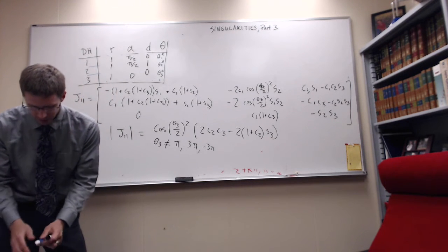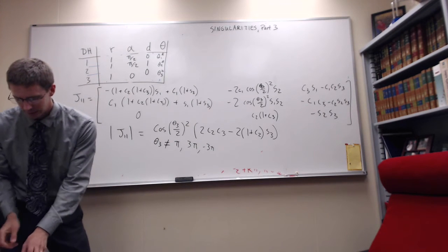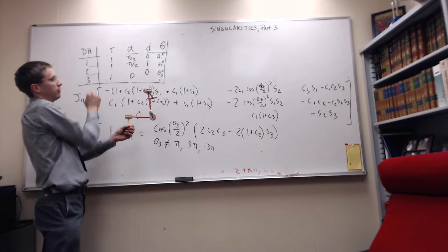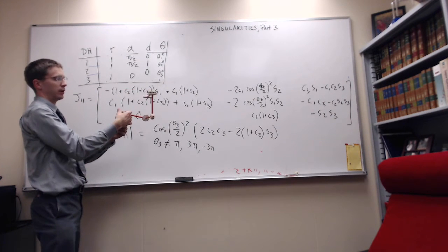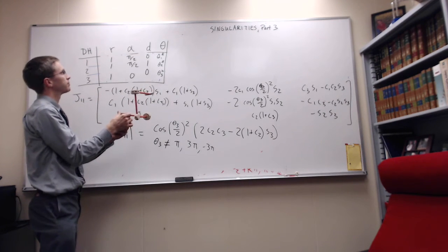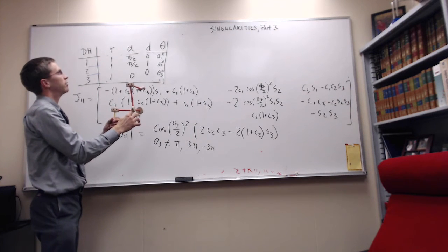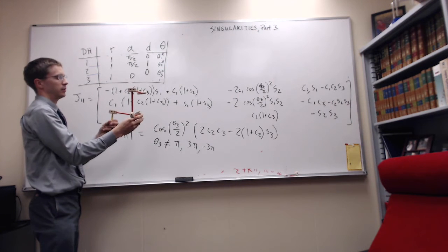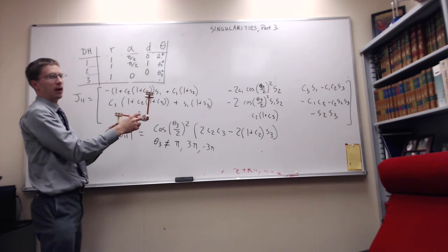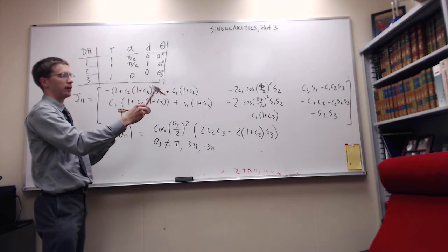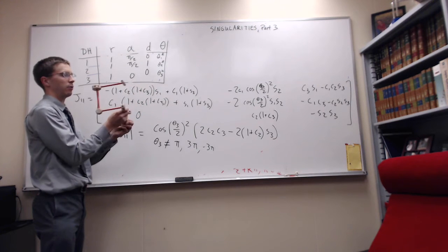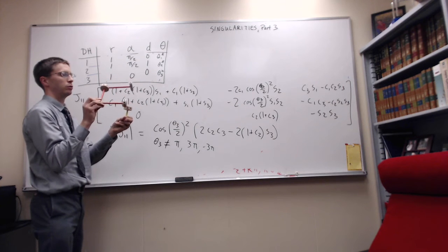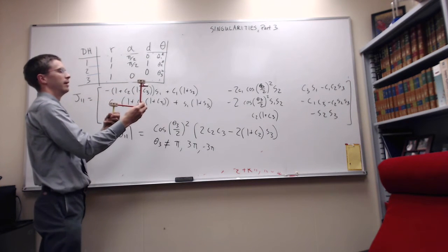And so what I've done instead is I've made a little model. So if you look at this, we've got our first axis is a rotation joint around the base angle. And it has both a radial offset and a link twist to this next joint. So this next joint, see how it is 90 degrees to the first, so we can rotate this around. So together we've got a rotation around the base length and then a rotation around the second length. So we can move this around quite a bit.